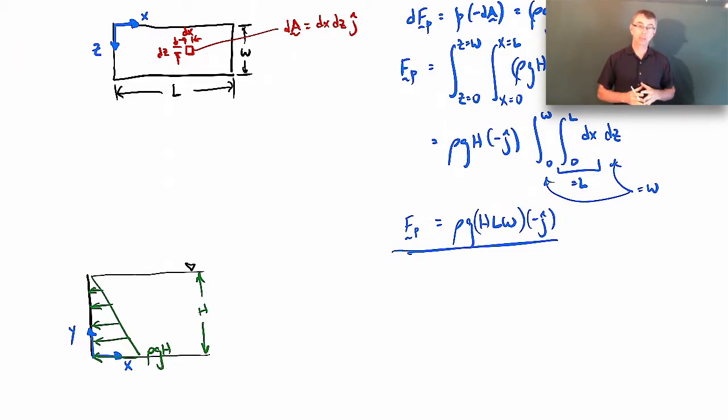Now here, when we think about pressure times the area giving me the pressure force, what pressure do I use? It's not clear because the pressure varies. Do I use the average pressure? The maximum pressure? 1/3 the maximum pressure? It's just not clear. So we don't have a well-defined pressure. In a case like this, we really should be using the integration approach, because over a small area the pressure and orientation are well defined. Over the large area, the pressure is not well defined.